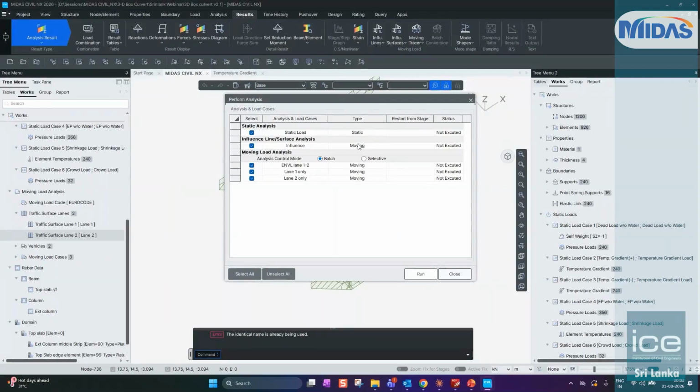Because if you have assigned everything and later on you find an error, it becomes quite difficult to correct the error. Sometimes in smaller models it is easier, but if you are working with bigger models, always run the model for one lateral case and one vertical case, at least to ensure that your model is working fine. If it's possible to run the eigenvalue analysis, then do that. It will show you wherever you have a disconnectivity in the model.